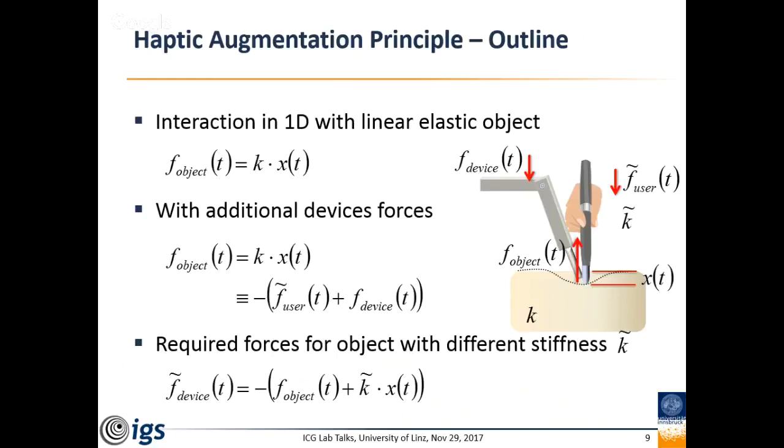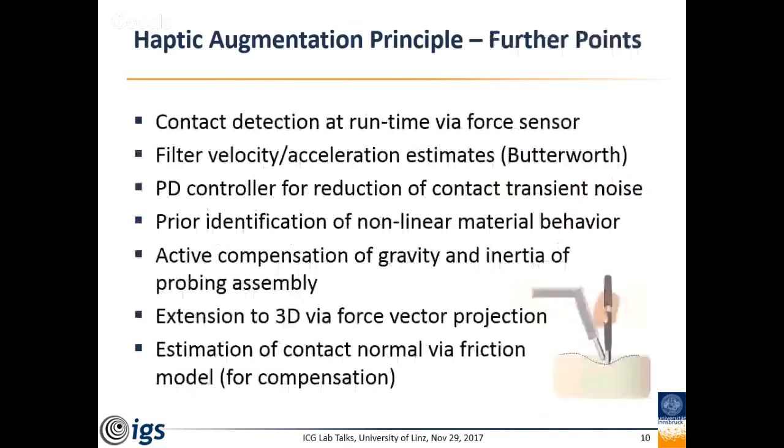There are a lot of other things to consider here. I don't want to go too much into detail. For instance, you have to know when to start rendering the forces. So you have to know when the contact happens. This can be done with a force sensor. So as soon as you touch the object, you know, okay, we are in contact now. Now we can start displaying forces.